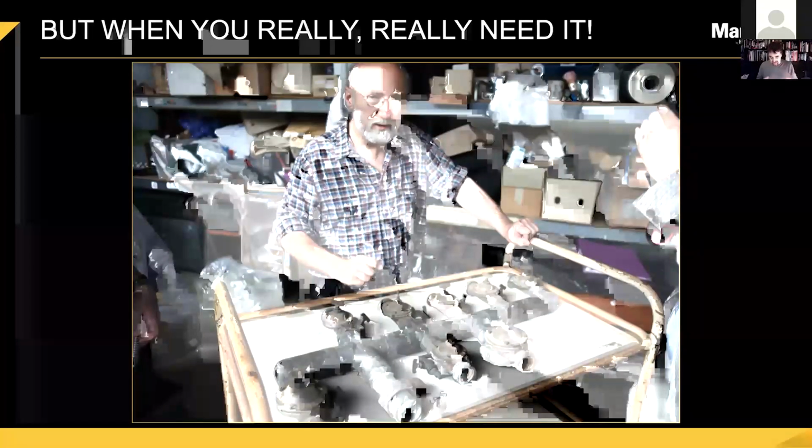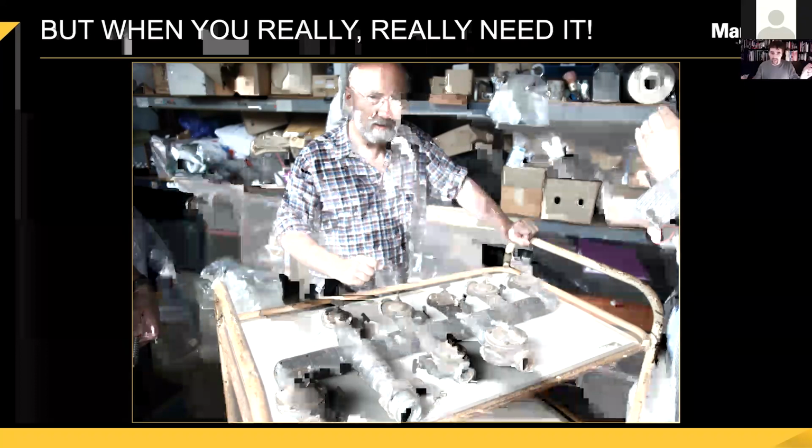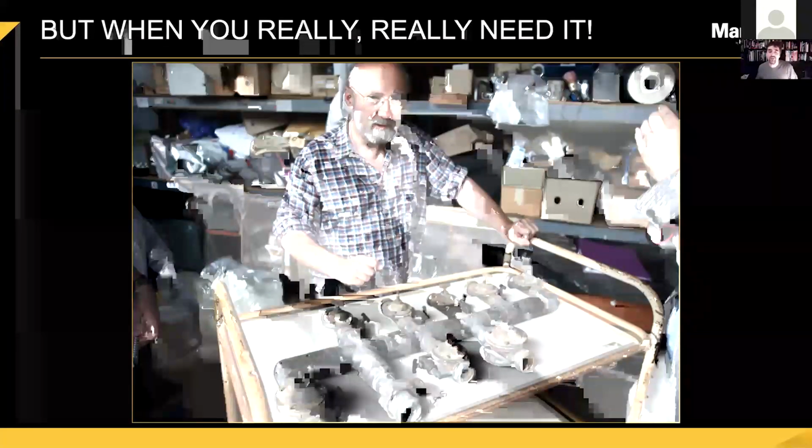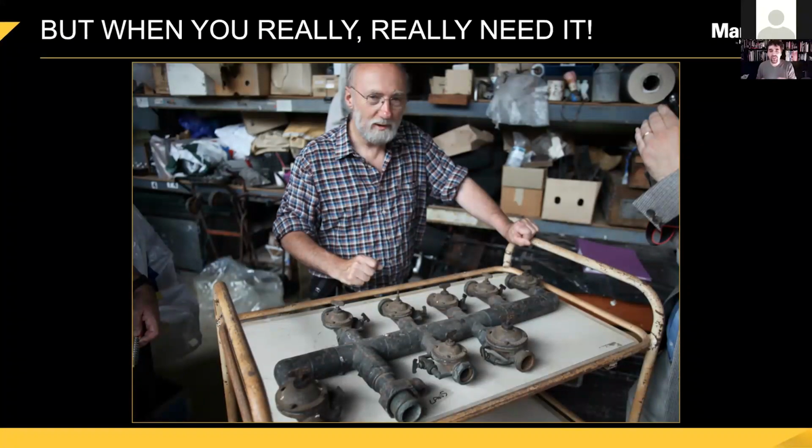So this is a gas table, I guess you could call it. It's a big main gas pipe with lots of outlets that would go off to different gas flames in different bits of the building. And they had taps on them, which are effectively dimmers. So you could now control the brightness of the lighting. But what you absolutely don't want to have happen is for the gas flame, when you fade it to zero, to go all the way out, because problem one is you can't ever get it to come back on again unless you can go up with a flame and light it.